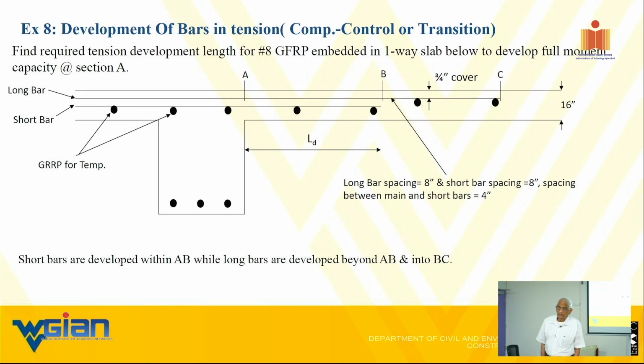If you can convert the bending forces into axial forces, you're in business, you see. What did I mean by that? The old arches are almost all axial-effect type structures, so they essentially converted the bending into axial effect.